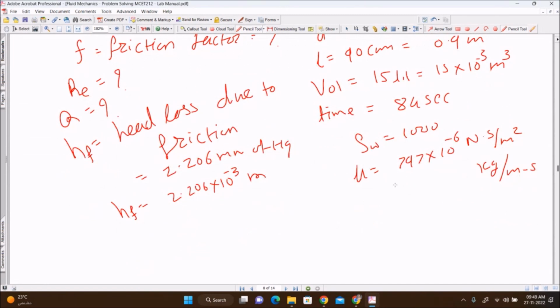As I told you many times, what is fluid mechanics? Fluid mechanics is applying the continuity equation, rho A V. My target is to find velocity. How can I find it? To find velocity, we need diameter, find out area, then discharge, and discharge by area will give velocity. This is the flow chart. Finish. Whenever you get velocity, put the formula, put values, and get the answer.